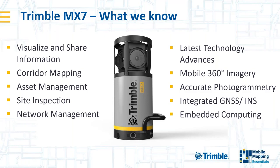So it's 360-degree imagery. We position things in the images using photogrammetry. We have an integrated GNSS and inertial system inside the unit, and an embedded computer that does all the hard work and records the data.